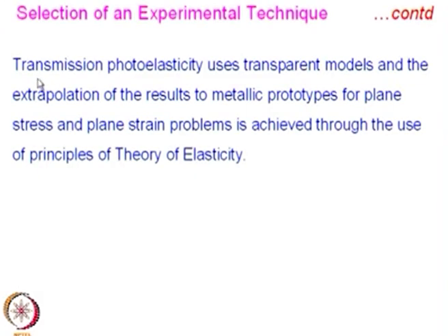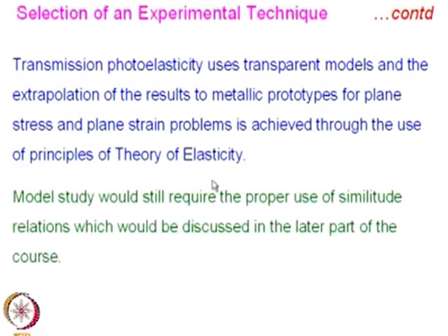Transmission photoelasticity uses transparent models, and the extrapolation of the results to metallic prototypes for plane stress and plane strain problems is achieved through the use of principles of theory of elasticity. You are actually using a model, and model study would still require the proper use of similitude relations, which would be discussed in the later part of the course.